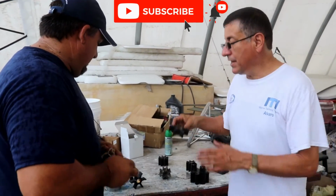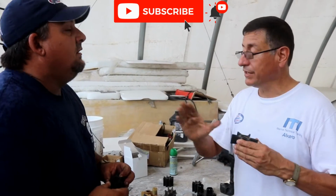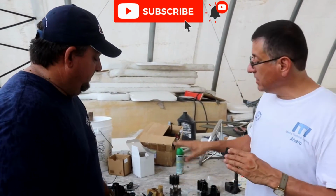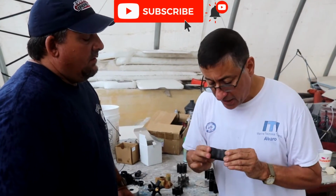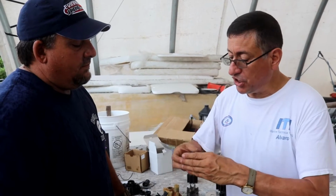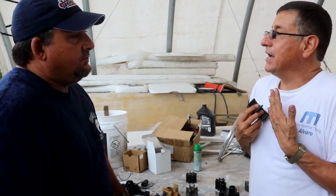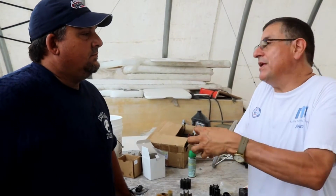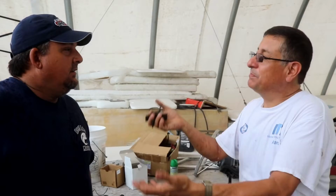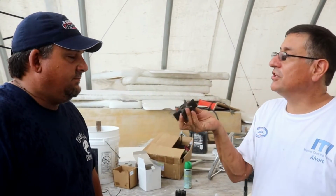The impellers are flexible impellers for raw water. This is mandatory in inboard and outboard. Absolutely. And the procedure, immediately after you remove the impeller, is to check if you have cracks, and check if all the blades are in good condition. Normally I recommend, if you remove the plate on the impeller, replace the impeller. Absolutely, because how many times do you spend removing the lower unit? You're already there. And this is not expensive.